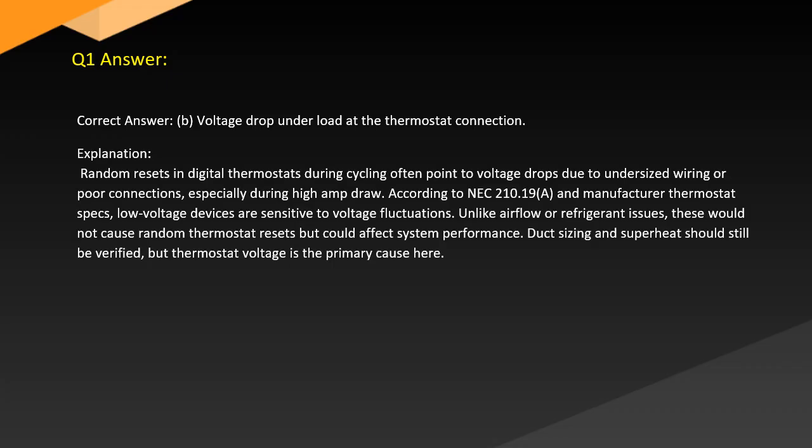According to NEC 210.19(A) and manufacturer thermostat specs, low voltage devices are sensitive to voltage fluctuations. Unlike airflow or refrigerant issues, these would not cause random thermostat resets but could affect system performance. Duct sizing and superheat should still be verified, but thermostat voltage is the primary cause here.